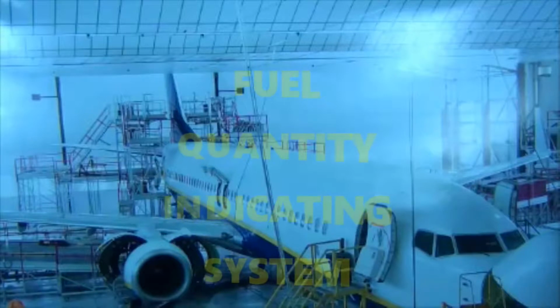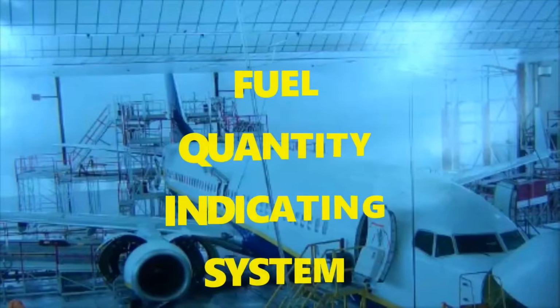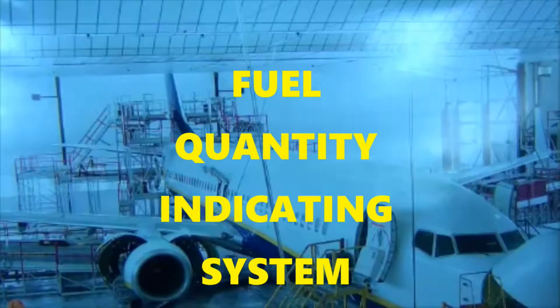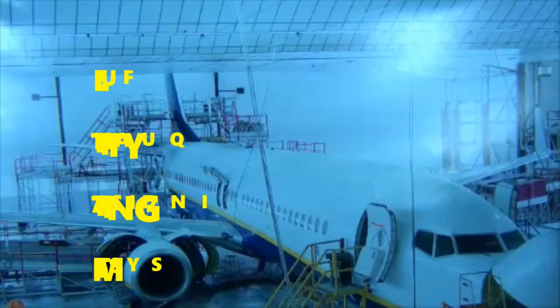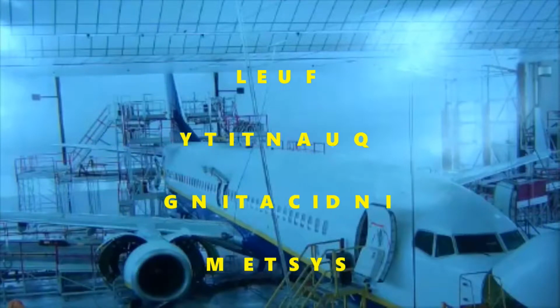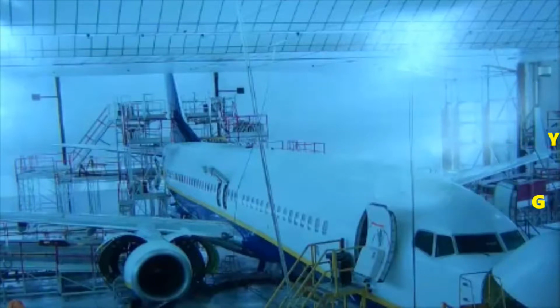The quantity indicating system, the FQIS that we have here, is a typical capacitance type indicating system. If you don't understand what that means, let us know, but that's pretty standard across different indication systems. Now, that's for in flight. If the plane's on the ground and you want to measure that fuel quantity, you're going to have the MLIs. So you have magnetic level indicators that give you the reading for what the fuel quantity is. And you have that in the left wing, right wing, and also the center tanks.